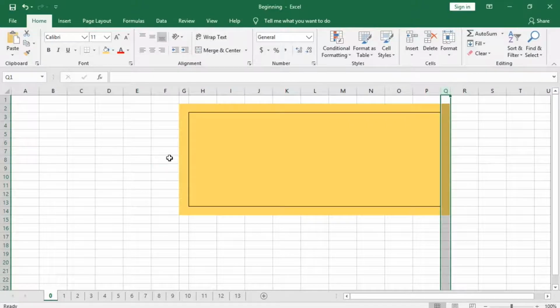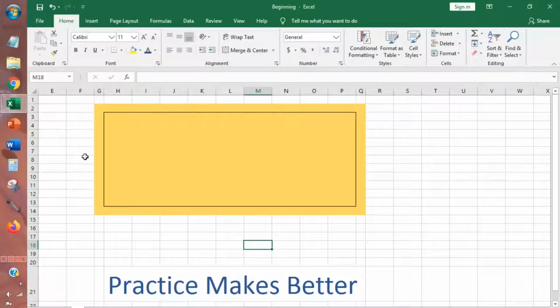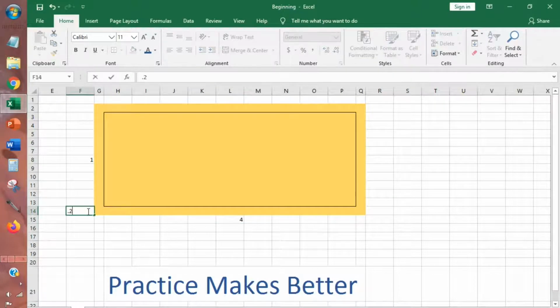Next, insert the pocket dimensions. You can use inches or millimeters for your dimensions. With my mouse, I place my cursor on a cell at the side of the workpiece. Type in a number and press enter. Then repeat for the bottom dimension. I chose to have a 1/4" border, so I add 0.25 to the bottom, tops, and sides of my pocket.